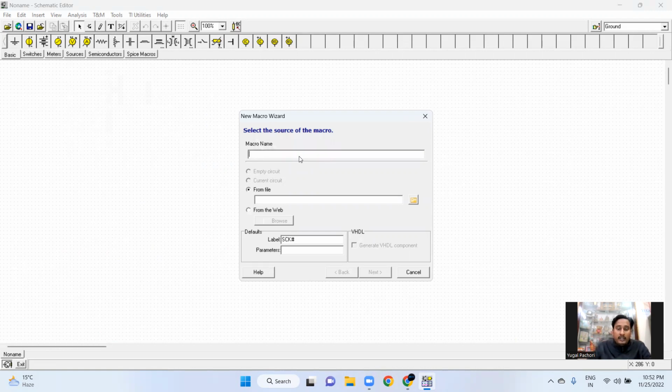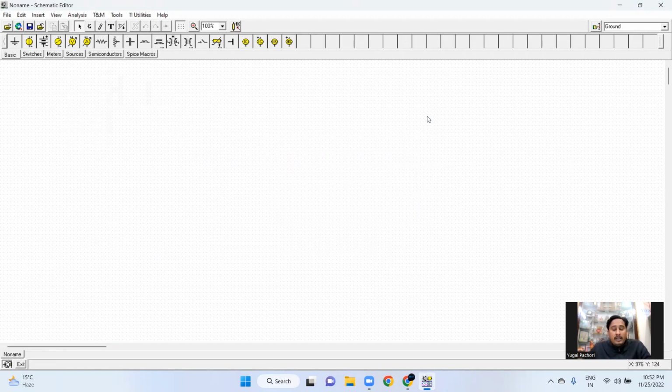Okay, so what is AD630? AD630 is an IC which is not available initially in this particular TINA-TI software. And if you want to add more ICs into that, then you need to download the SPICE file, the LTspice model file.